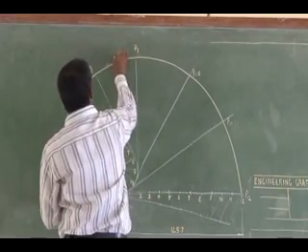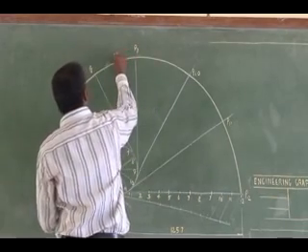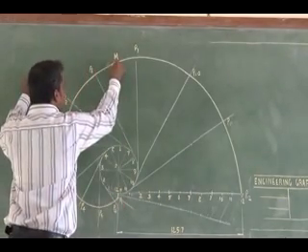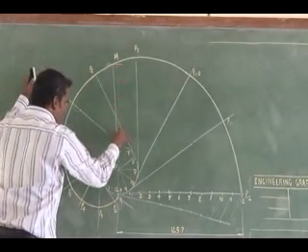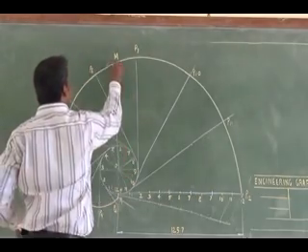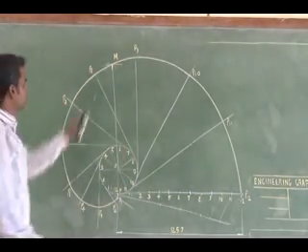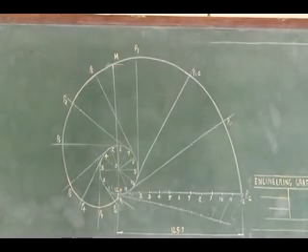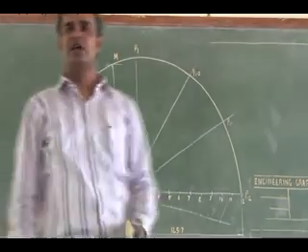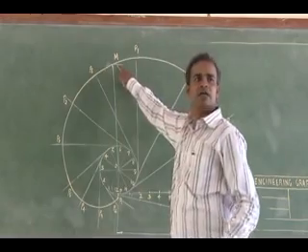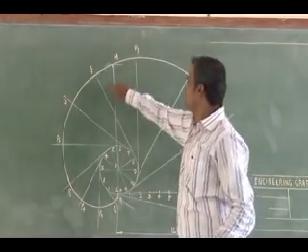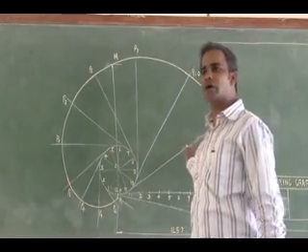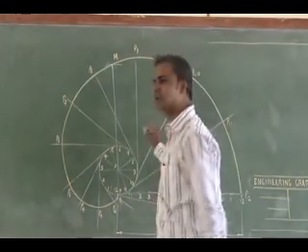So this is my point M that I am interested in. The length of this point from the center is given, 90 mm. Listen, all of you. How to draw the tangent and normal? From center to this point is 90 mm, and it falls in between P8 and P9. How to draw tangent and normal? It is different from polygon. See here how I can draw it.